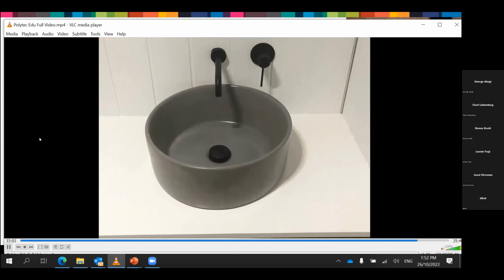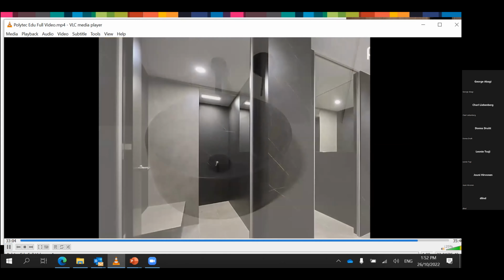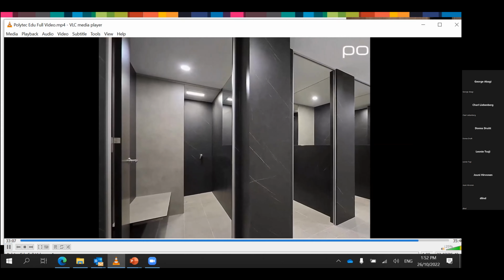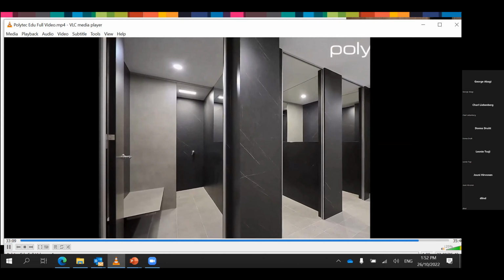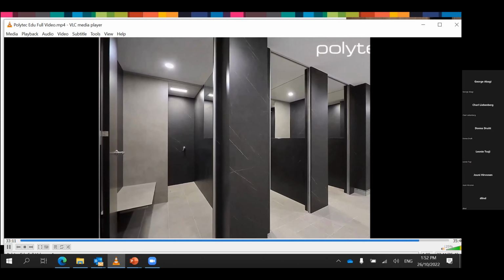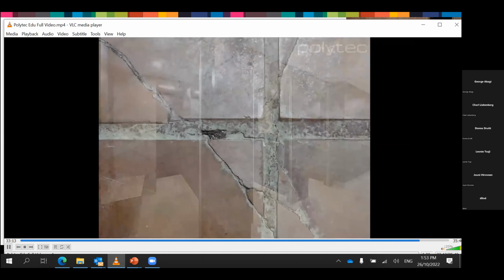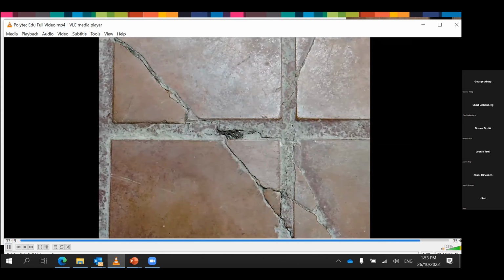For bench tops and wall lining. When selecting materials for wall linings in washrooms, 5mm compact laminate is a low budget but effective option for wet areas and high traffic areas. Unlike ceramic tiles, compact laminate is far less susceptible to cracks and damage.